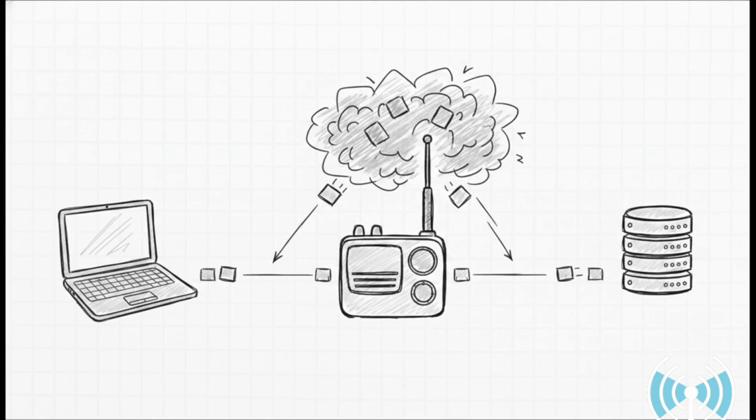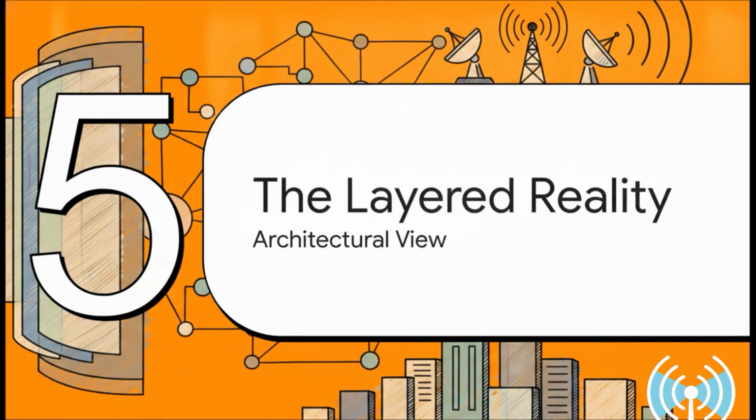But it completely depends on available bandwidth and network reliability. If your RF environment is congested, well, your IP traffic is going to suffer. And remember, not all tactical radios actually support RTP-based audio natively, which means you have to do some special planning for interoperability.